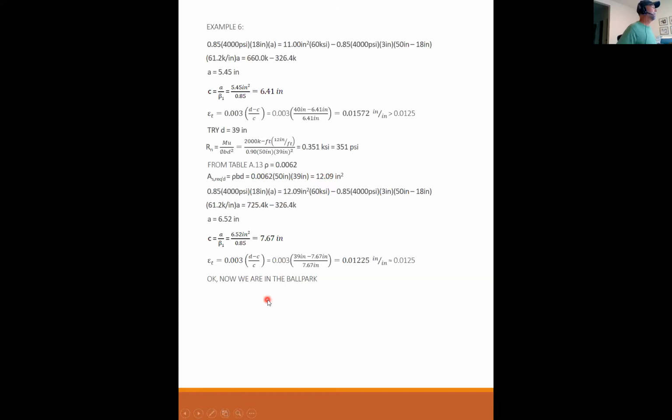All right. So any other questions? Anybody have anything else on your mind? Professor, I missed that first part. You said the max positive moment cracks at the bottom and the top of the beam is in compression, whereas the max negative moment is opposite of that? That's correct. Yes. Okay, I wrote it. Thank you.